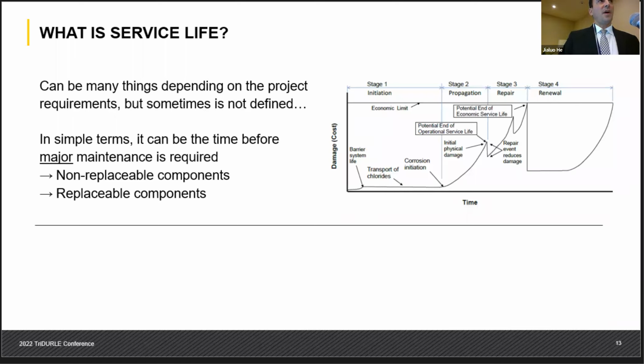Now if we think about that, you can meet all the durability requirements in a code, and it doesn't mean that you're going to meet a service life. If you want to go through the exercise, go through any code and run the calculations to determine the service life requirements for that structure under a certain condition. You can change the different exposure conditions and you'll see the service life change. However, the concrete is durable per the code. But it's likely not allowing the concrete to be serviceable for the amount of years that you want to meet. So you need to understand that.